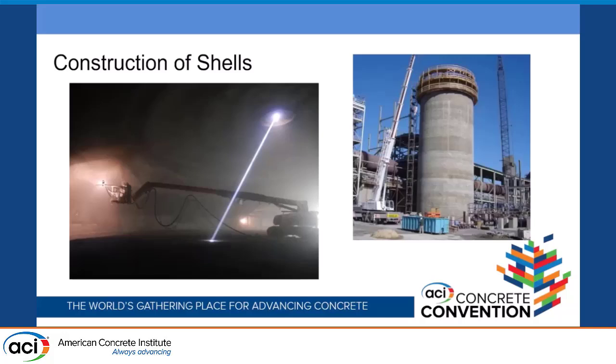But once again, if you have hard forming and it's an arch, and they're going to decenter it, they've got to make sure that they counsel with the engineer and the designer, because your decentering forces, depending on where you take the posts out and what you do, could be higher than your shell stresses in the end. So how it's going to be constructed needs to be considered by the designer and worked out with the contractor during construction.